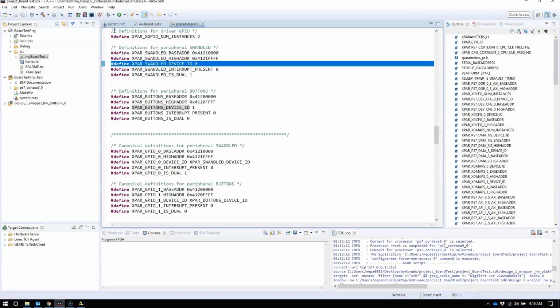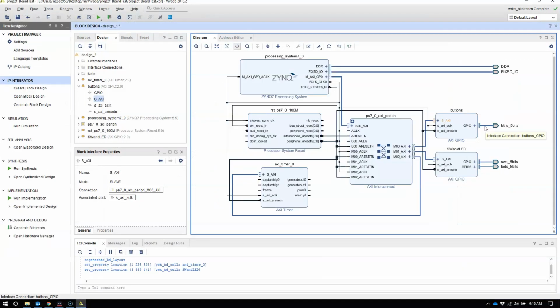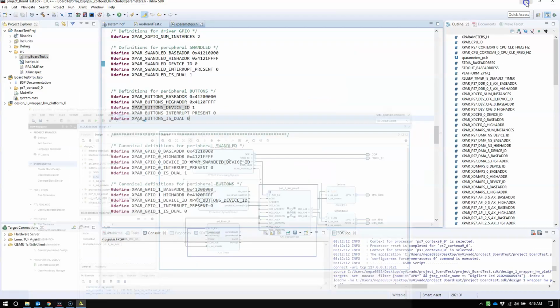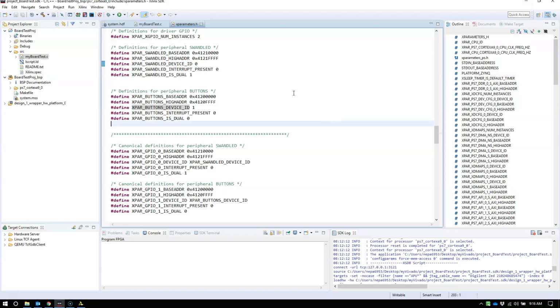Now the question is, what is the name of the device for part C, where I asked you to turn on the MIO7 LED that's connected to LD9 when I press the button PB1, which is MIO50. So when I press that button, I wanted you to turn that light on. Well, where is that connected? It's connected to this ZYNQ through the fixed IO right here. Okay, so, well, what is IO? Well, general purpose IO.